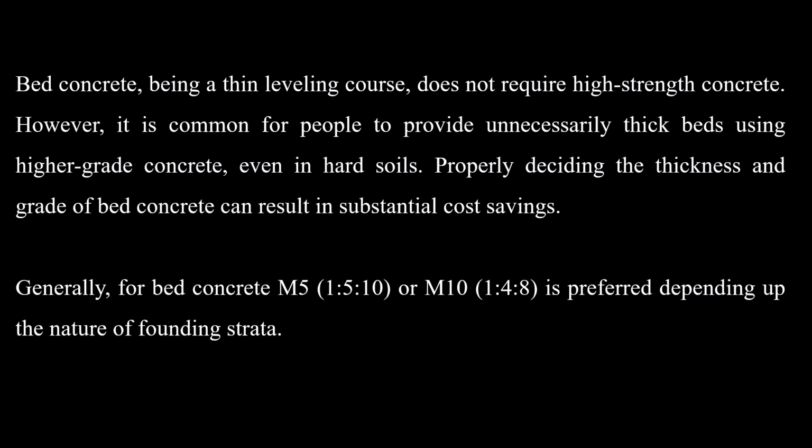Bed concrete, being a thin leveling course, does not require high strength concrete. However, it is common for people to provide an unnecessarily thick bed using high grade concrete, even in hard soils. Properly deciding the thickness and grade of bed concrete can result in substantial cost savings. Generally, for bed concrete, M5, that is 1:5:10, or M10, 1:4:8, is preferred depending upon the nature of the founding strata, which has to be decided by the engineer in charge.